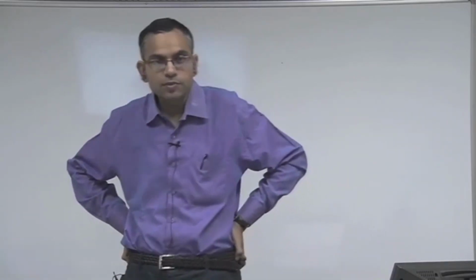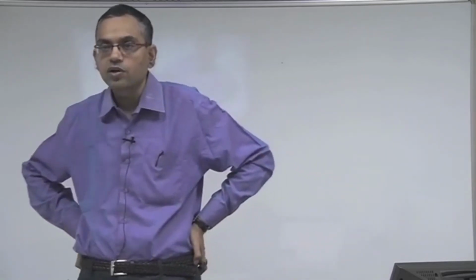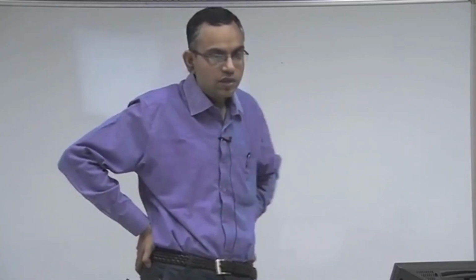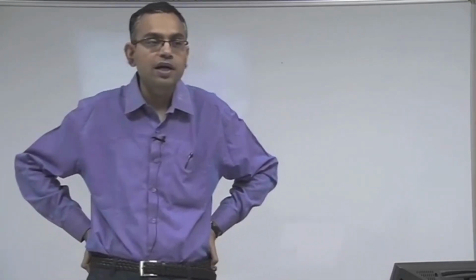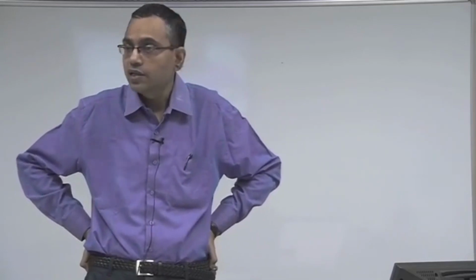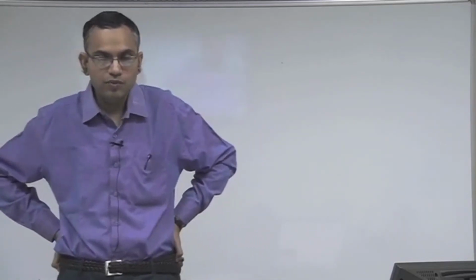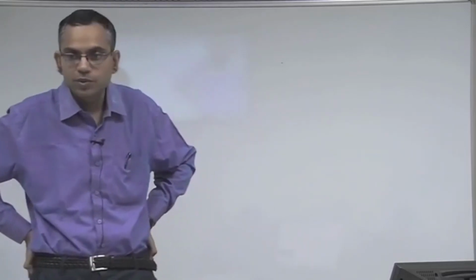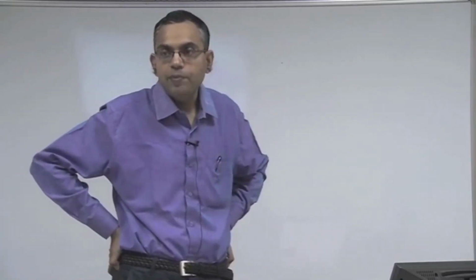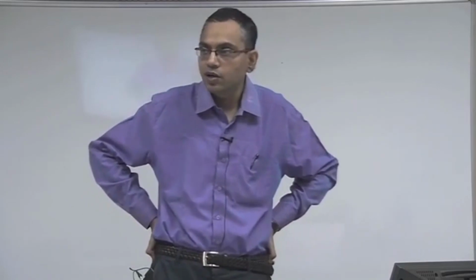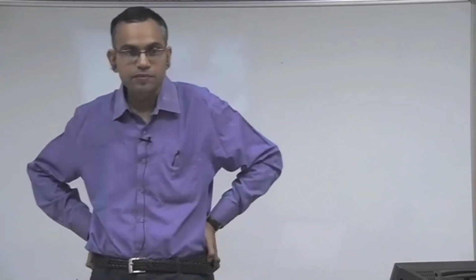In the Lucas-Washburn equation we got an expression which is a modified version as compared to its original form to include the effect of slip. Now the question was how can we describe the slip, that is, what should be the appropriate slip length, and how can we get it. If we can get the slip length, we can use the Lucas-Washburn equation to predict the capillary filling characteristics, the displacement, velocity, acceleration as a function of time. But the question is how do we get the slip length.